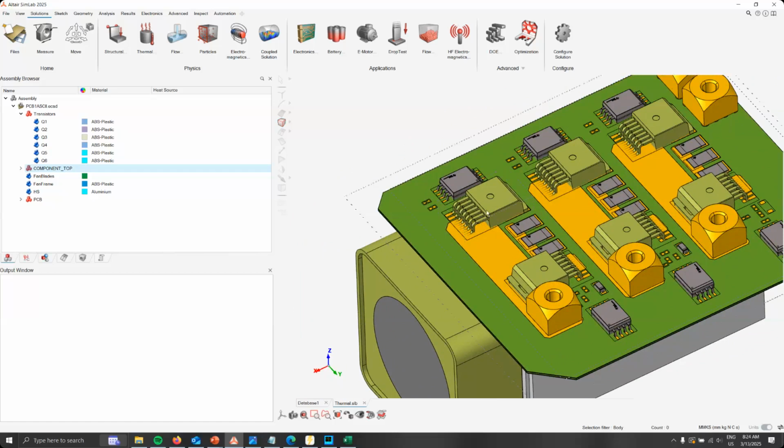Simplifying your thermal loads onto boxes is really helpful in these cases, and this is the same thing we did for the MyWay case. Originally in the MyWay model, there were these very complete models of the switching devices, but we simplified them to boxes so that it was easier.